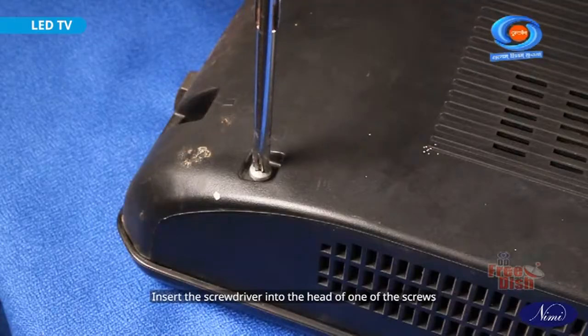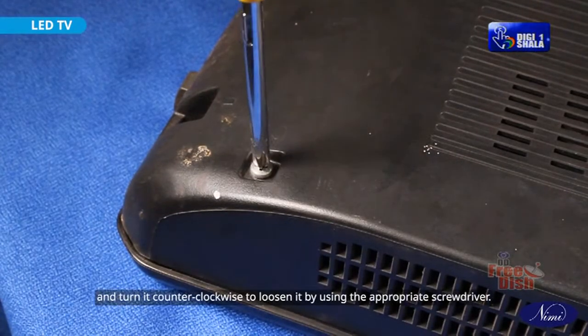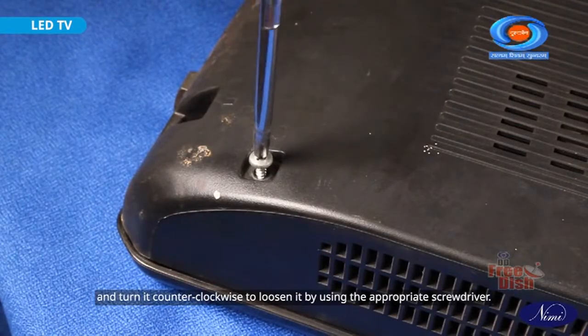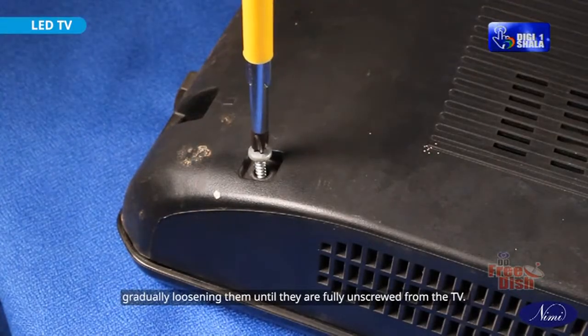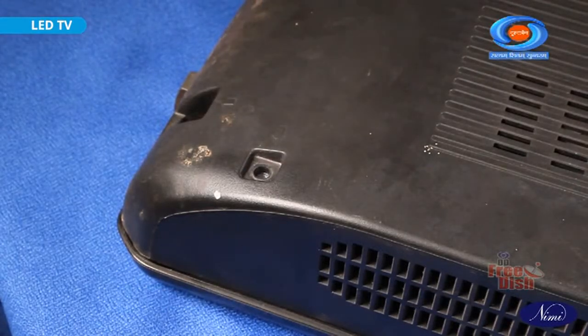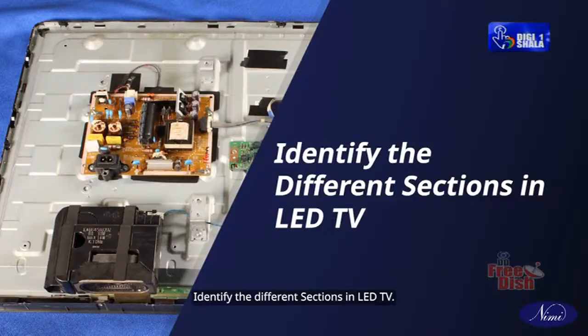Insert the screwdriver into the head of one of the screws and turn it counterclockwise to loosen it, using the appropriate screwdriver. Repeat this process for each of the 4 screws, gradually loosening them until they are fully unscrewed from the TV. Remove the outer cover to show the main body of the TV monitor. Identify the different sections in the LED TV.